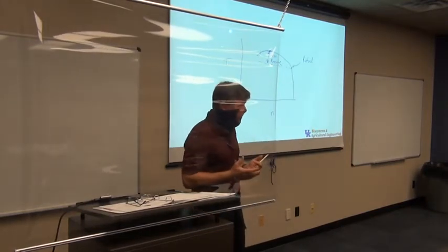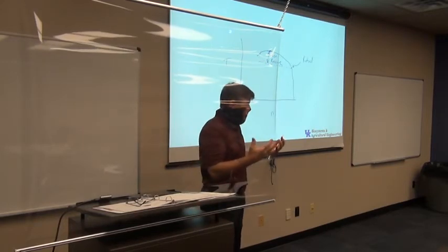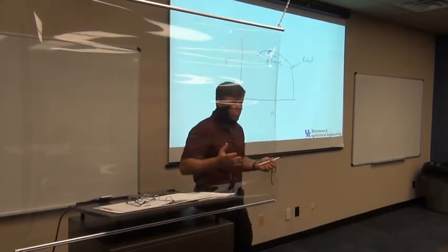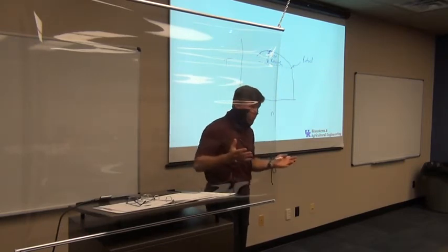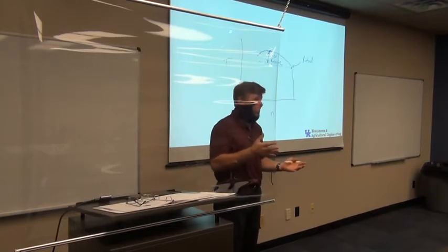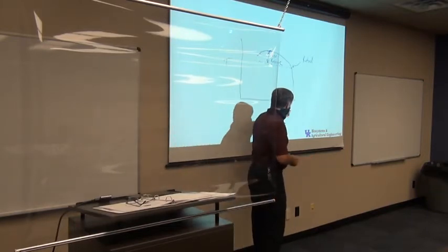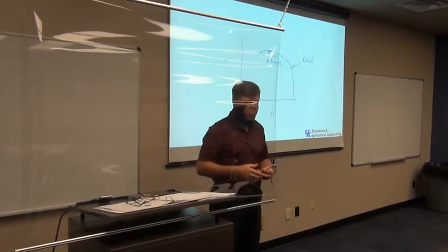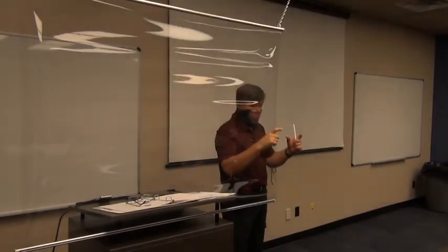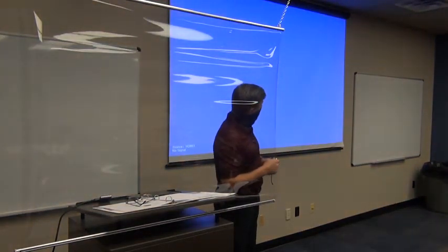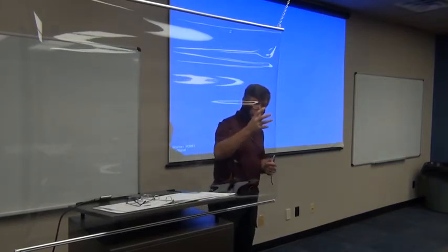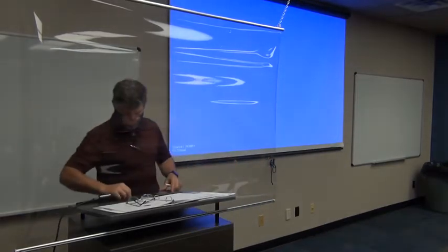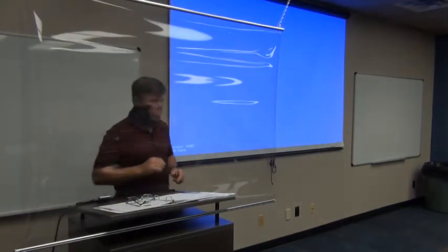So we talk about a rated point where engineers have decided this is what we're going to specify as the rated performance for that engine. We could choose anything we want, but typically it's around there. That might be the peak power, and they all might be kind of close. And then we talked about, for tractors, there's a typical speed where we get the right power takeoff speed, where that power takeoff is going right at 540 or 1,000 RPMs. So there could be like three different points, and on a lot of the tractor test reports that you were looking at, you get all three of those. So what the torque rise is officially rated at, it's measured from the rated point.